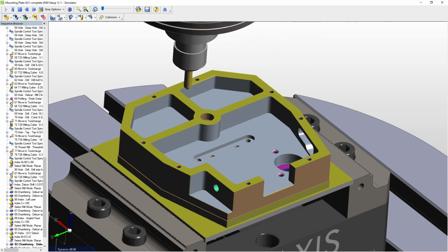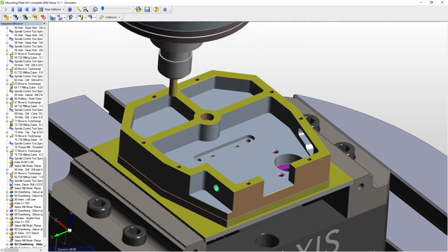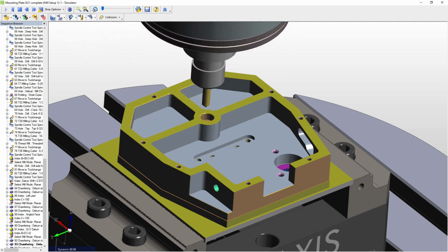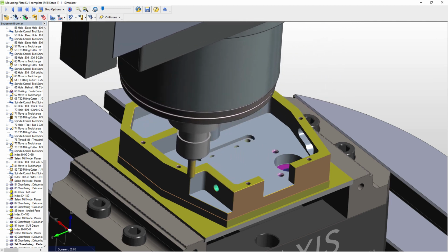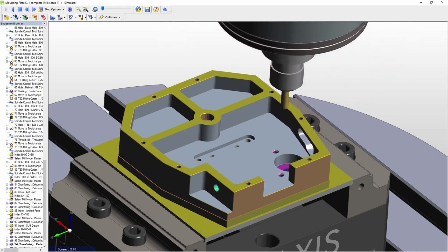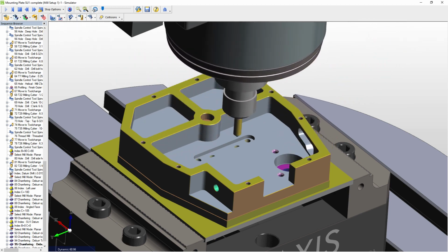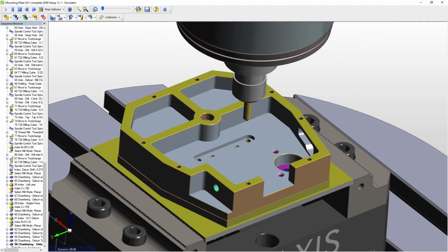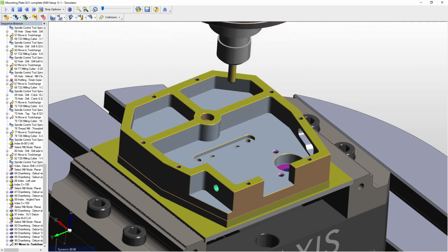Finally, we move back to 0-degree position and deburr all the top side pockets, holes that were not already countersunk, and that'll include a couple of lower steps. Everything here is collision checked, and the visual of simulation allows us to confirm whether what we see here matches our intent. In this case, it does.